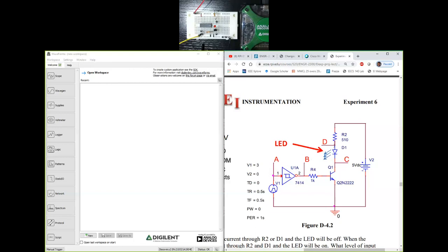There are four different points that are highlighted in red in this circuit. A is the voltage source, B is exactly the opposite of A, but now it is going to be digital, so it's going to be a binary signal. So it's going to be opposite or out of phase with respect to A, but it is going to sort of look square, like a square wave.